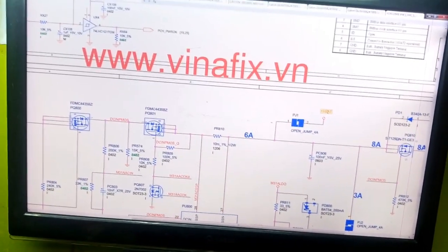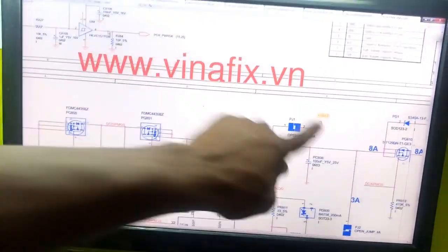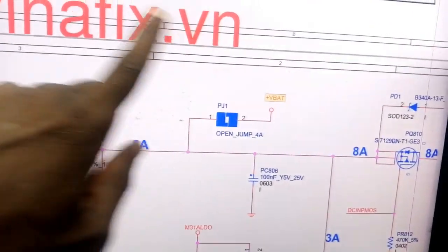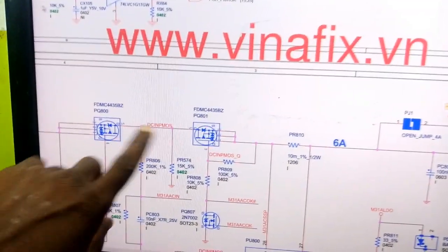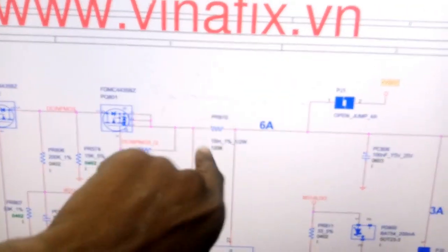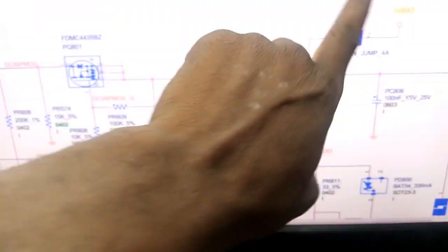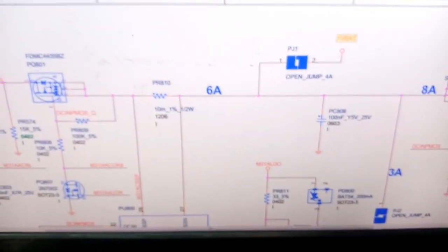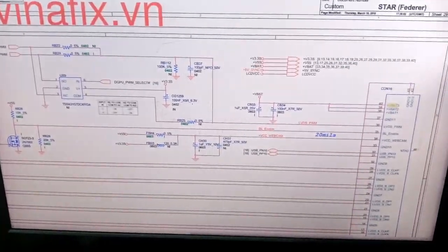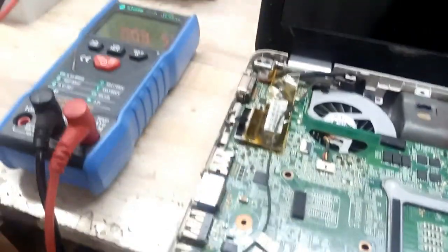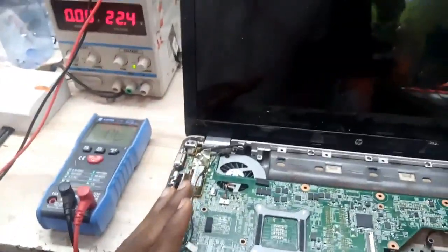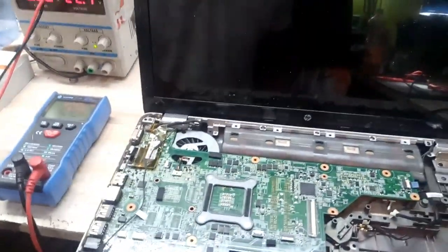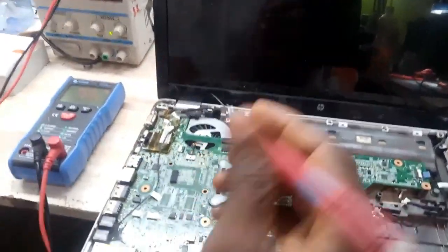Exactly this name is the name we have on that particular pin of LVDS, and as you can see, this is the birthplace, the ultimate source of that particular 19. So therefore there is no need for looking for any pin. So what I'm thinking now is that there must have been a kind of disconnection internally on this motherboard. What I'll do is tap 19 volt from any source and jump it there. Let's see what we have.